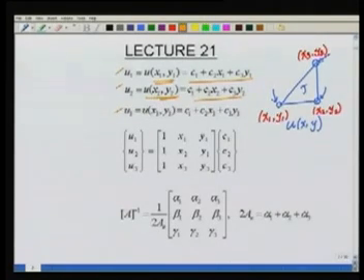So I assume that I know my function u of x, y. Given that function, I know the values u1, u2, u3, which can be written in terms of the coordinates of the 3 points and these unknown constants. We want to find these unknown constants c1, c2 and c3. So the 3 values of u are given as a combination of these unknown constants c1, c2, c3. Now the job is simple. It's a 3 by 3 matrix. So we have to invert this matrix to get c1, c2, c3 in terms of u1, u2, u3. That's about all we have to do.